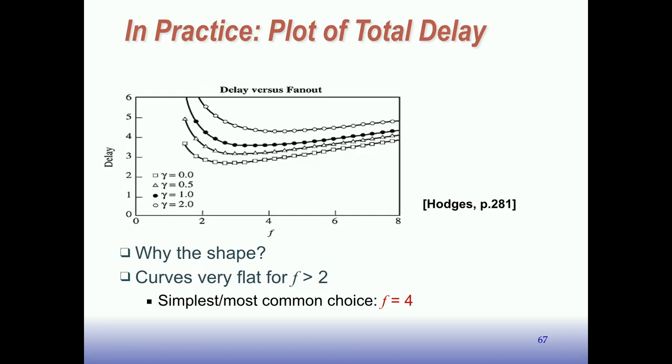So you see this in the circuitry that's for driving pads. The circuitry that drives the signals that exit chips will have staged buffers, and they'll have something like 4 in series or maybe 6. And this also, earlier, I guess last week, we were talking about FO4 delay, fan-out of 4 delay. That's why that's an important number to look at, because when you're fanning signals out, oftentimes you do it with a fan-out of 4 and do it in multiple stages rather than doing it all at once, because 4 ends up being kind of a magic number for this fan-out delay optimization.